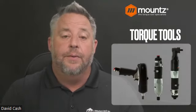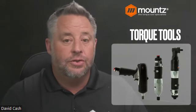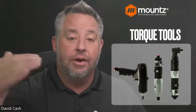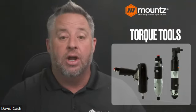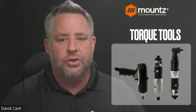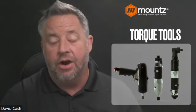And then another type of tool is going to be a pneumatic style of tool. Again, these particular tools compress a spring, but the big advantage of using a pneumatic tool is that we can go much higher in torque values than you can with an electric tool. There are electric torque screwdrivers that can go up to 80 inch-pounds or so, but most of them live probably under 25 or so inch-pounds and below. But with the pneumatic tool, you can go much higher.